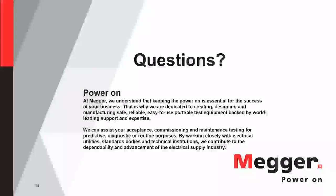No, and as I said, what I recommend from what we've seen is if no information is given, you want to go right at contact separation, where that arcing zone starts. As those contacts separate, there's no more direct connection, so you're going to have an arc going on inside that circuit breaker. So then you just go from there, and the reason we use 10 milliseconds is, a lot of times from an IEC world, 50 hertz, and so that's half a cycle. So you could even do 10 milliseconds or 20 milliseconds afterwards.